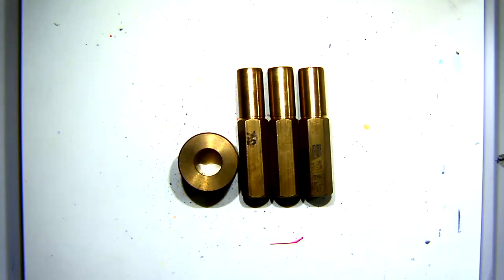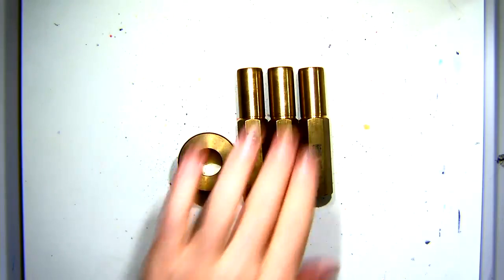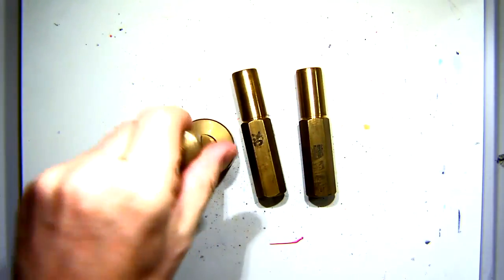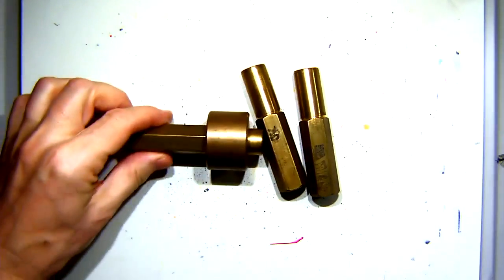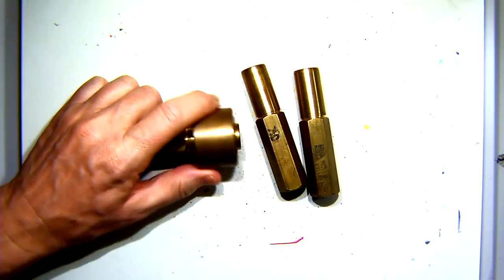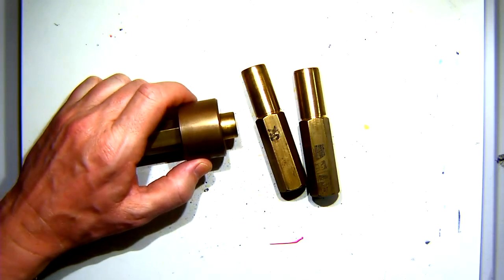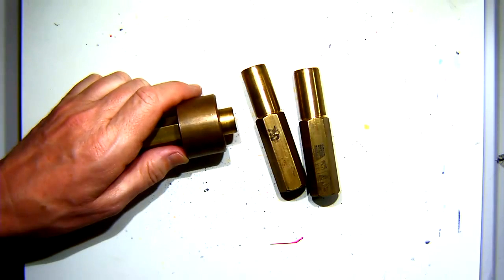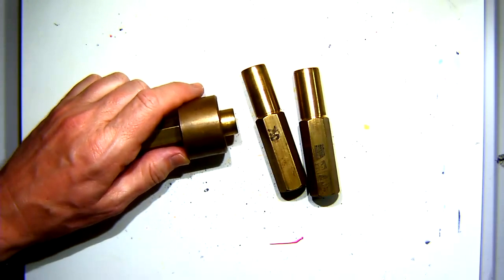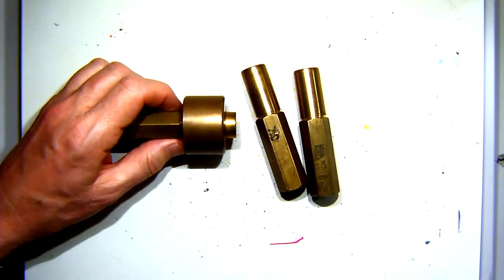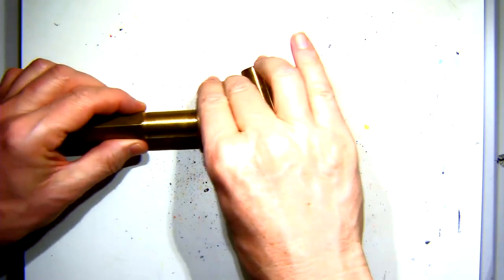The shafts, by comparison, there's only 3, but imagine we've got 1,000 of each of those: clearance, transition or interference shafts. Each and every one of those shafts, I'll just pretend that this is the clearance. So it goes in pretty easily. Now, if I had thousands of shafts, their diameters would all be slightly less than that 10 millimetres I was talking about. It might be 9.95 to 9.98 or something, but they'll always fit in.